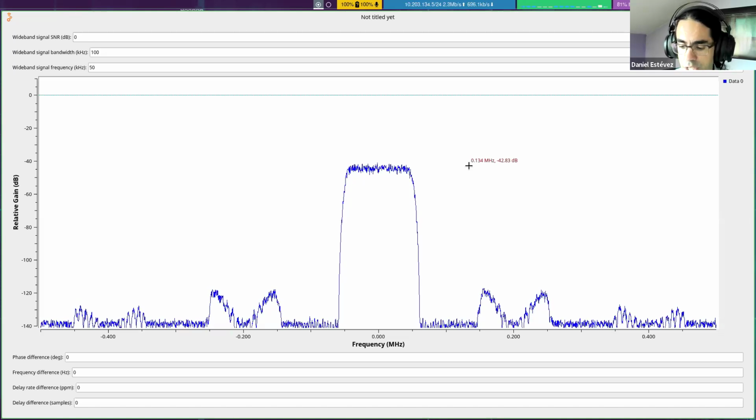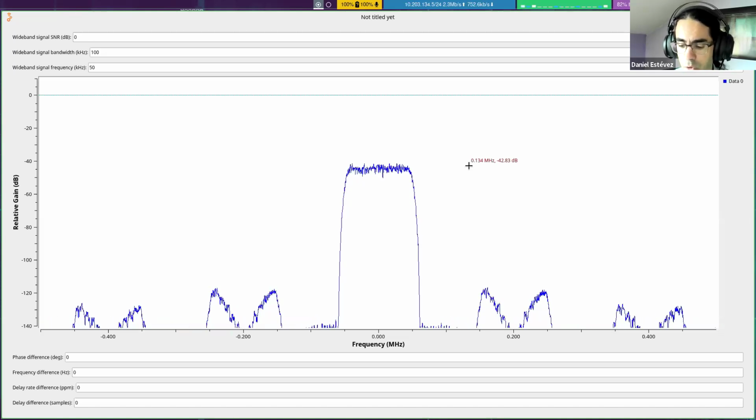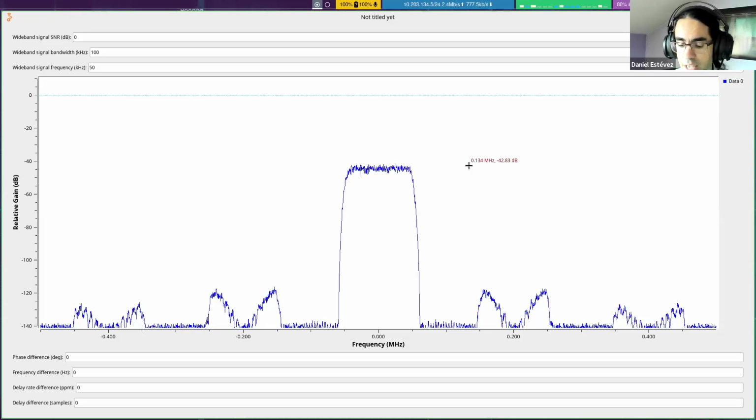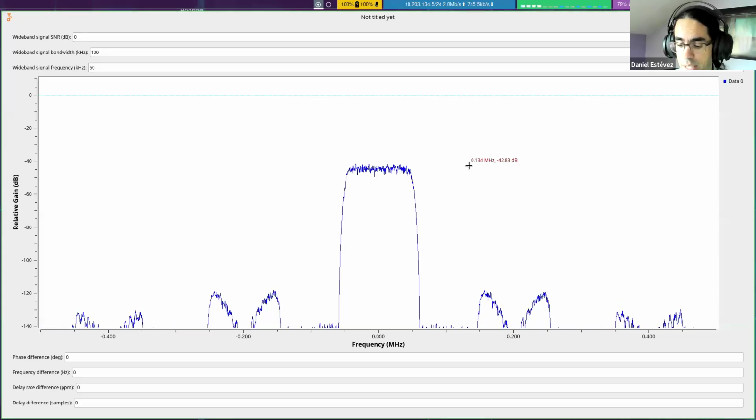And as the geometry changes, because the source on the sky is apparently moving, the relative phase difference between the antennas will change. And so we see a phase change over time. And a phase change over time is the same as a frequency. So we will see a frequency difference between the two antennas. I know this is somewhat conceptual. We will see that in GNU Radio in a second. But before that, maybe any questions? If something I said wasn't too clear, we can stop and explain again.